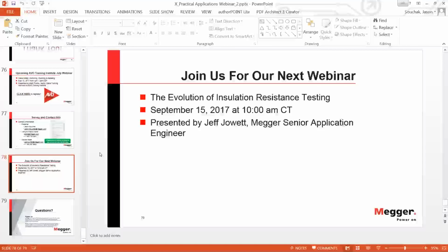So the PD would be for high resistance defects like voids in splices and terminations, and the leakage current tells you whether you have anywhere a low resistance situation, typically a mechanical defect from the installation process. So that is really a catch-it-all type of test, which is described in IEEE 400.2, the monitor withstand test for commissioning a new cable. I think it's a very powerful tool to do that.